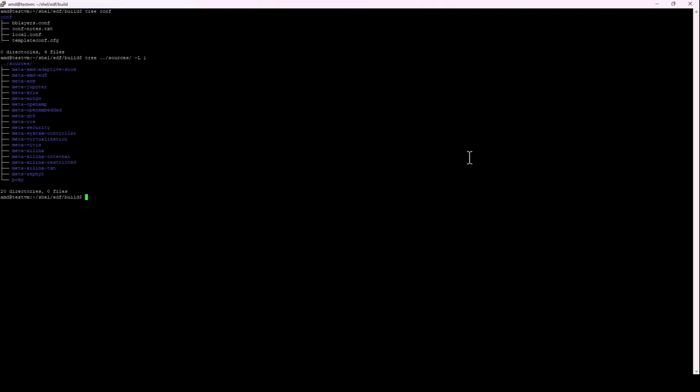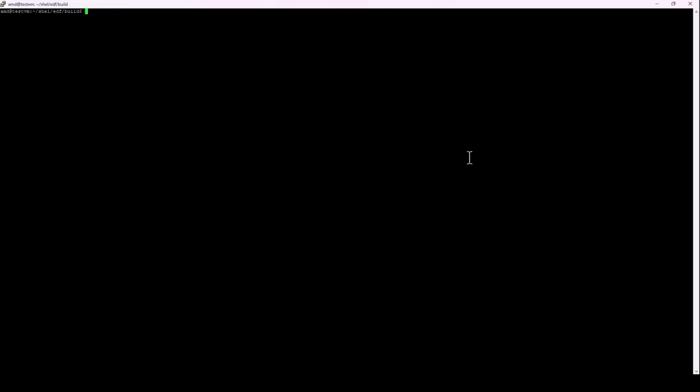Now that we've created and reviewed the Yocto project environment, it is now time to create a custom Linux OS based on the system device tree previously created. To do this, copy in the pre-built template bsp.yaml file for the VEK385 containing custom configuration information using cp command as shown to the build directory and give it a custom name like versal-custom.yaml.